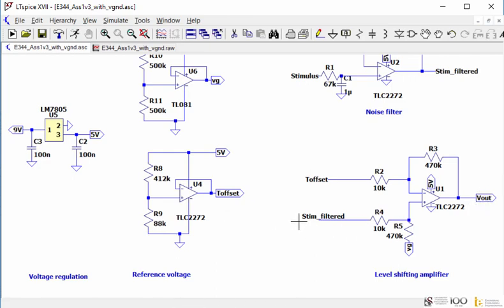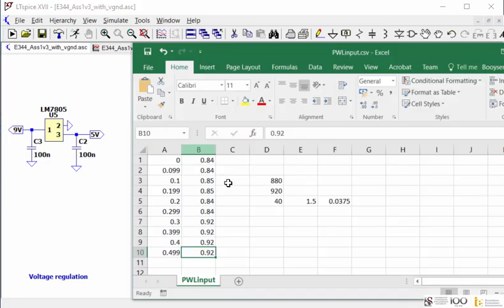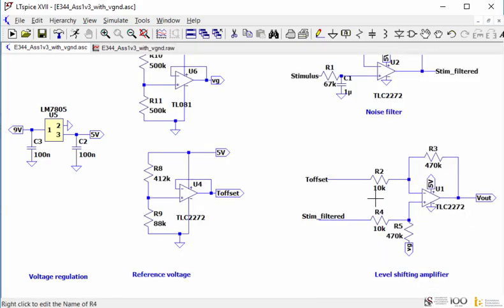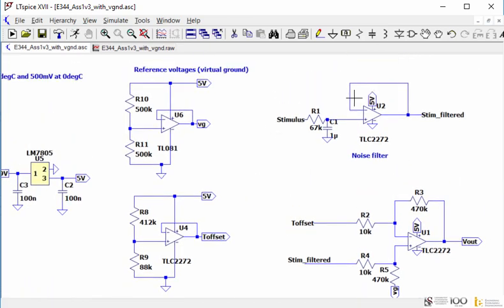So the 920, what will be subtracted is the 880 multiplied by a gain of 47, and that output will then be close to 4 volts. The same if it's at the bottom range, 840 millivolts, subtract the 880, I get 40 millivolts. That's gained or amplified by 47 gain, and that gives me something close to 0 then on this side here. Okay, so let's just look at the filter then.